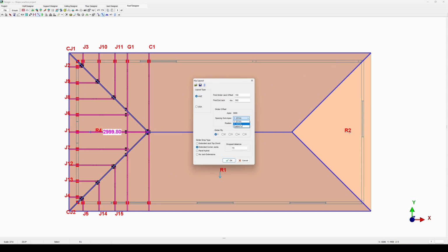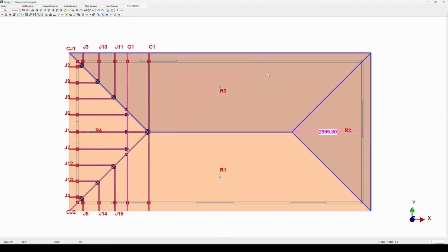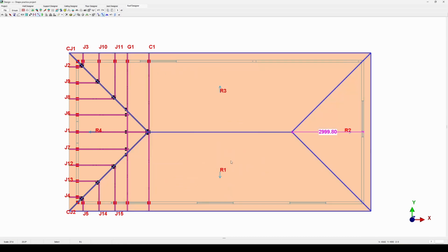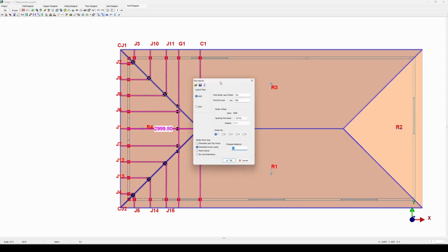If you place this on the second position, as I'll show you in this next example, we go to the opposite end, insert my hip tool, and place it on the second position, as you'll see there, number 2, which is the distance away from the end of the wall. We'll click OK. You can see now the difference where the girder is placed on the first position away from the apex versus the opposite end being on the second position with a common truss separating those two spots.